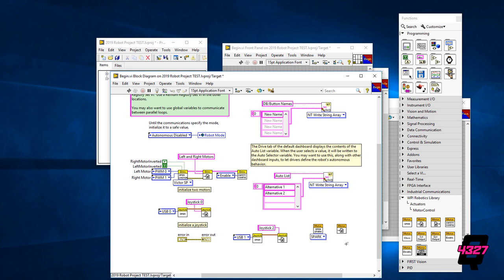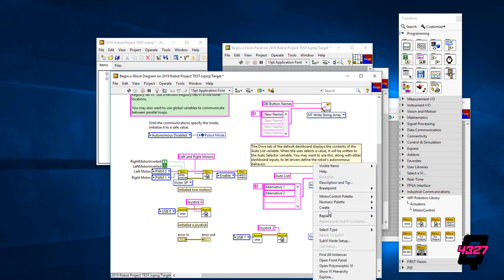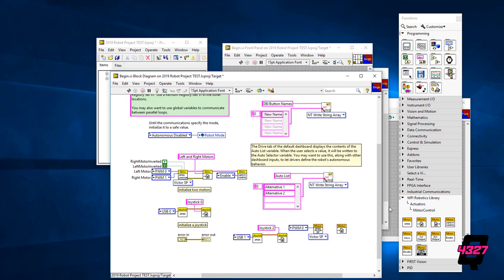Under the open icon, you will again need to select the type of speed controller you'll use on the robot. I will choose a Victor SP for this tutorial. Other speed controllers allow other options, such as the Talon SRX, which uses CAN bus wiring instead of PWMs for sending information. We'll save that for a more advanced video, but for now, let's get this motor up and running.